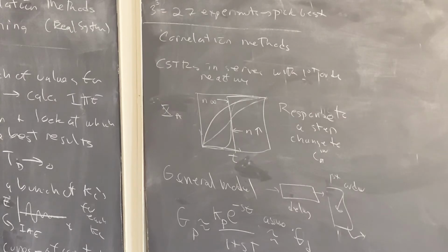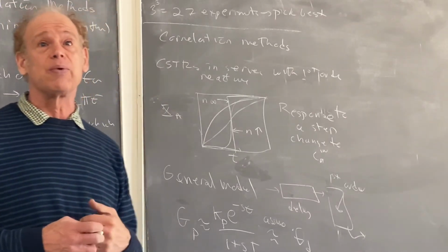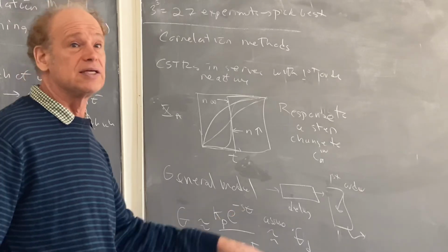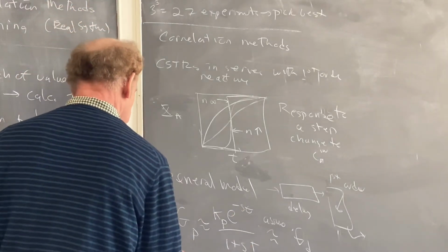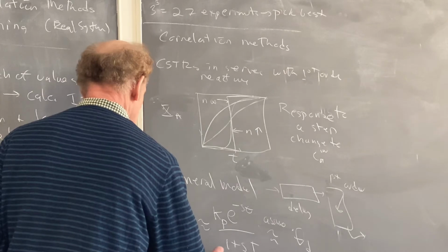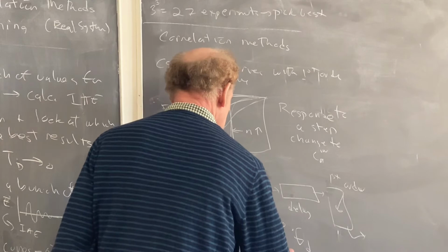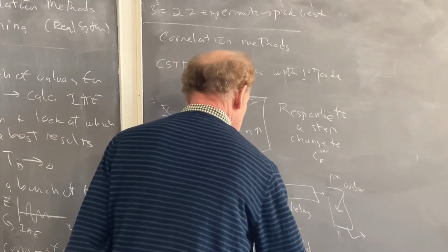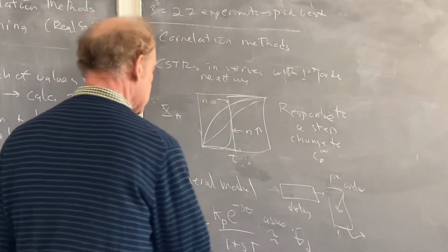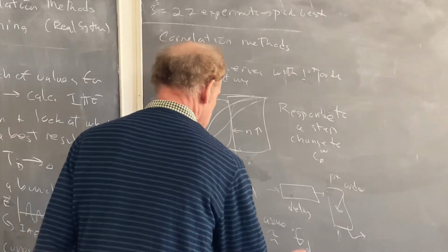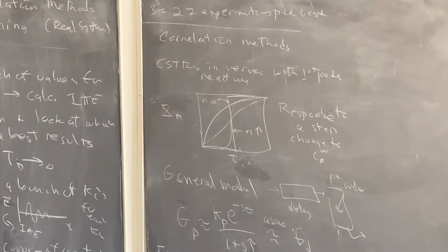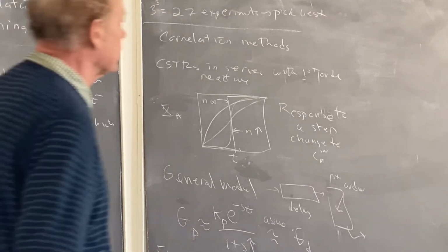So what we would try to do is take the real situation that we have and try to fit it to this model to get 3 parameters, a KP, a T, and a theta. And let's call this tau instead of T. So we want to get those values for the real process. It's not going to be a perfect fit unless you happen to have a CSTR and a plug flow reactor. Any other system, that's going to be an approximation.